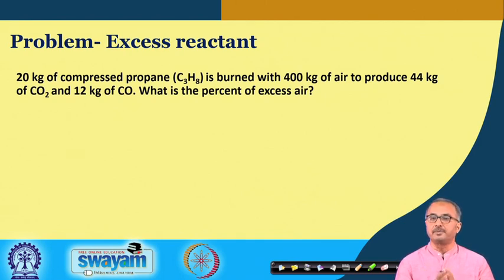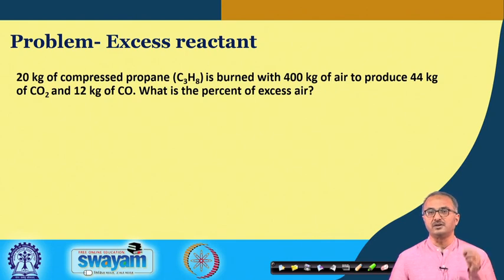we have to separate oxygen from the air. So, it becomes a very costly affair. So, many times for combustion or oxidation purposes, we use air. But in that case, it becomes very diluted because of the large amount of nitrogen present. Anyway, whatever stoichiometric amount of oxygen is needed will be supplied through this air. And when we are using air, we also have the problem of handling more volume than what is exactly required for the particular combustion process.